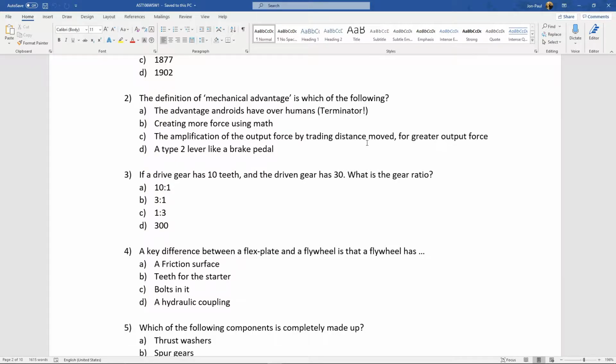If we are on the highway and you want to race and you pull up next to me and I'm in sixth gear in my Blueberry and I don't downshift, I just leave it in sixth, I get absolutely no acceleration because this is the other end of the spectrum. However, sixth gear will carry me from 40 miles per hour up to, I don't know, maybe 110 or 120. I have no idea what that car does. You see my point here, though? First gear was 0 to maybe 20, but sixth gear is from 40 to maybe 120.